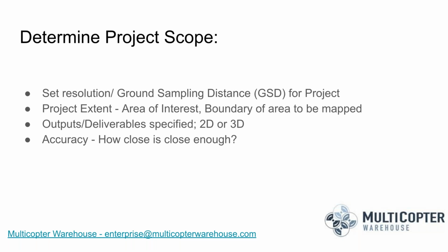However, it's not a bad camera, but really the camera on the Phantom 4 Pro with that 1-inch CMOS global sensor is more ideal for photogrammetry than what you'll get from a 4K video camera. That 4K video camera is ultimately going to produce roughly an 8.2 megapixel image, and that's not quite as good as a... Right. The Mavic Air 2 has that 48 megapixel sensor, but it's 48 megapixels on a half-inch sensor. So you can't just look at megapixels. You have to look at sensor size as well. The sensor size is certainly a big part of it. We have that here in the presentation we're going to talk about in a bit.